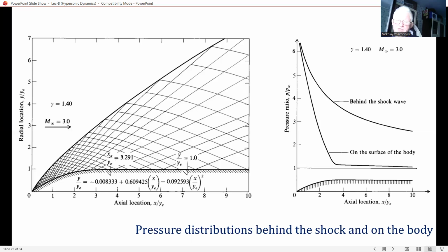The results shown in both figures are included here only to illustrate the use of the rotational method of characteristics for a two-dimensional body, and to emphasize again that the method is a reasonable approach for the calculation of two-dimensional and axisymmetric inviscid hypersonic flow. You know, most practical aerodynamic problems involve three-dimensional flow. The method of characteristics can also be applied to such flow.